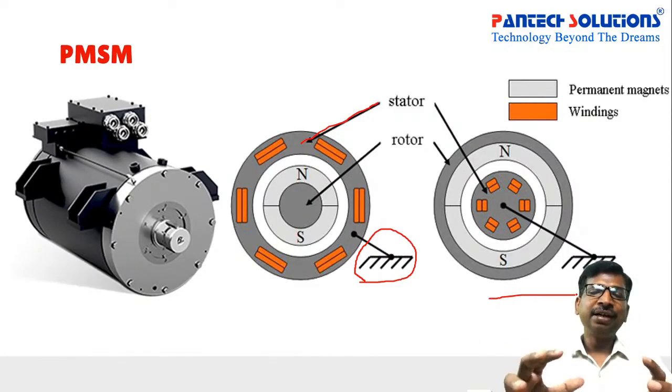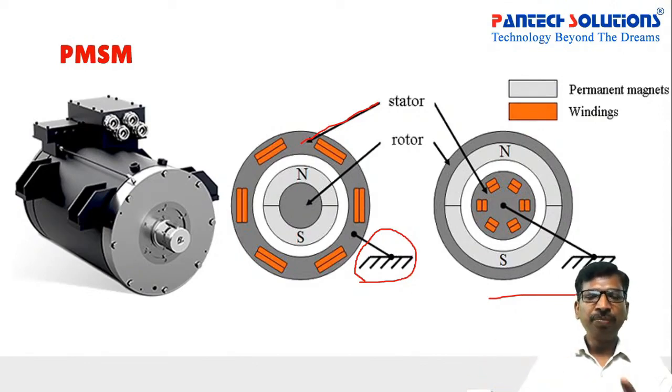If you do that exercise, then we can match this as an exact wheel for any electric vehicle application. So due to that behavior only, the future transportation will be entirely EV. Everybody tries to replace it with the induction machine. Earlier, in all the EVs, only the induction machine was used. But nowadays BLDC and PMSM, and sometimes some manufacturers are also trying to use SRM, the switched reluctance motor, and the synchronous reluctance motor. There we can get a higher torque to handle the entire load without any disturbances. So due to this kind of behavior, people are trying to use it.